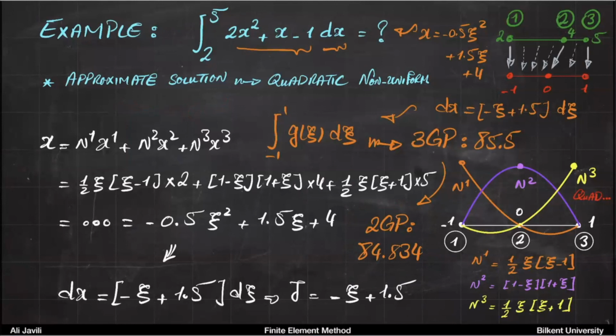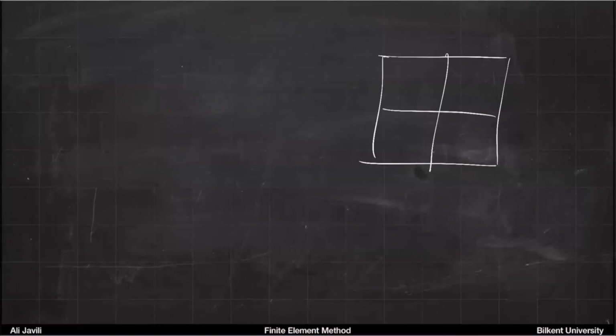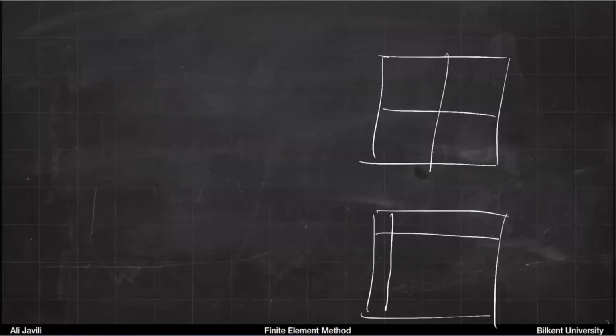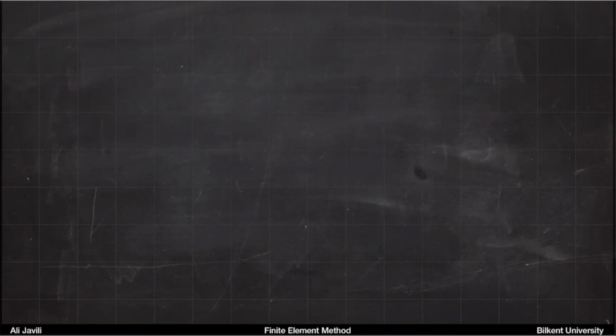Okay, and then again, if you do finite element discretization, there is always this step about discretization, about meshing. And there is this thing called structured mesh. And if you use something like Abaqus or COMSOL or something like that, they also have features to test the efficiency of the mesh. So if you have an element like this, try to mesh it like that. If instead of doing that, you mesh the same thing like this, you introduce an error into your finite element solution. A uniform mesh is always better than a non-uniform mesh. Also from other aspects, but I just mention it from, let's say, an integration viewpoint. It's always nice to have a uniform mesh because then it ensures a uniform mapping.